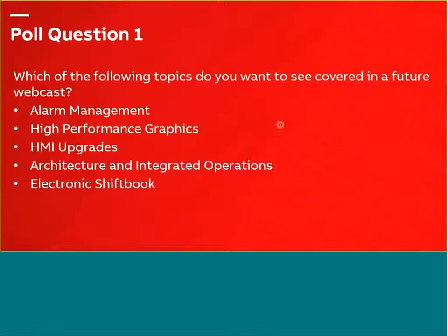From the standard library, we have some users, as Mark mentioned, who want colors as the high performance philosophy at the site, whereas other users might say that for them, high performance is different shades of gray. So the library that we have allows for flexibility. We use universal logical colors, so we can go in and change the database to say my gray across the entire plant should be a little darker, a little lighter, or change the gray to be red or yellow from the logical color database. So we do have a starting point, but we tailor it based on what is relevant to the site.